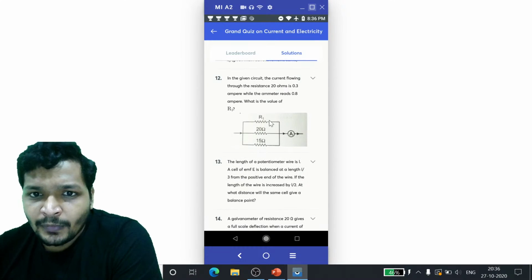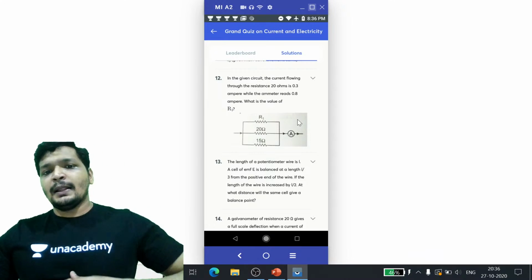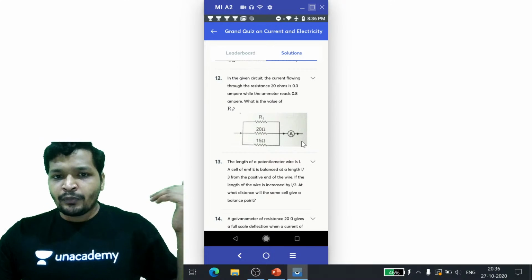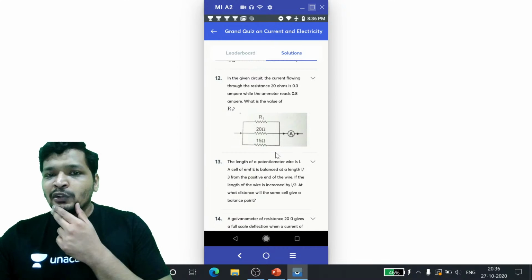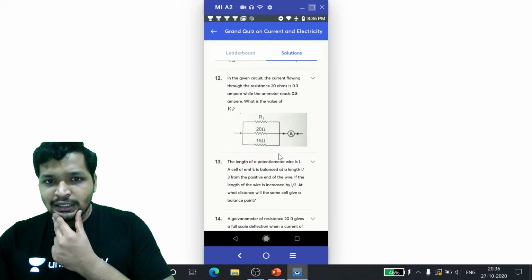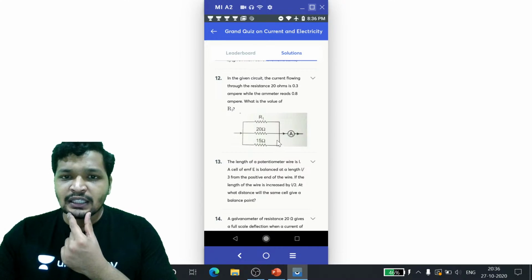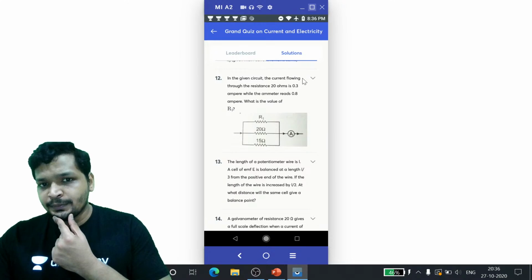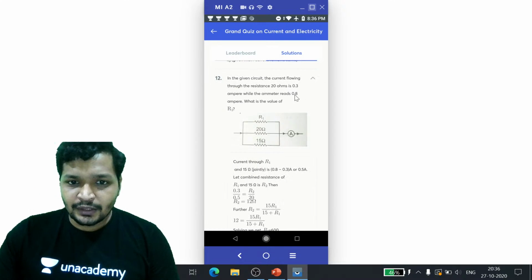Okay, this one, how do you go about it? In this, total current is 0.8. You take I1 plus I2 plus I3 is going to be 0.8, and then you will say R1 is to R2 is to R1. Else, one more thing you could have done, very simply, not going through all the hassle of solving each and everything, you could have simply taken the parallel combination resistance. From that we could have simply guessed R1. I don't know if the solution is also in that way.